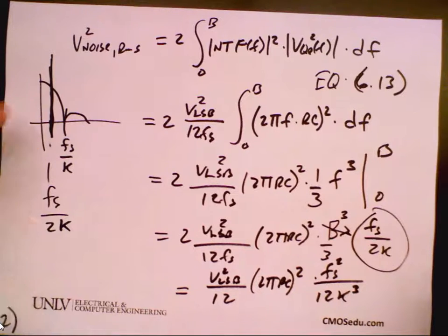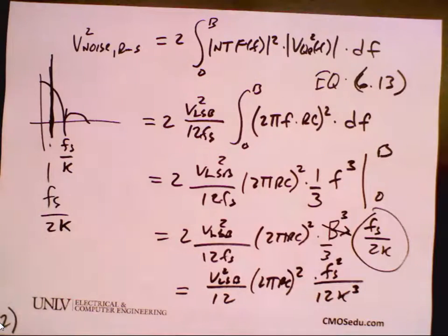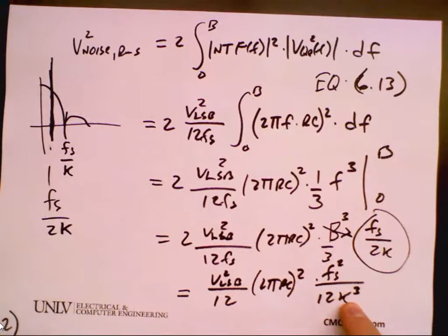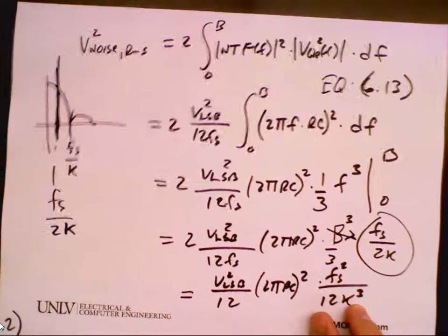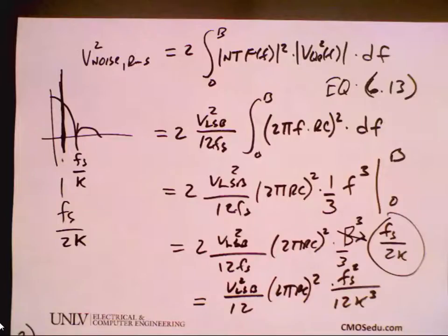Okay, so just make an observation here. If I increase k, just looking at the equation, what happens to the noise? If I increase k, yeah, it goes down, which means I'm reducing the bandwidth of my filter, which means my comb filter has more delay elements and I'm choking off the noise. The drawback is, of course, the bandwidth is reduced as well. Okay, makes sense?